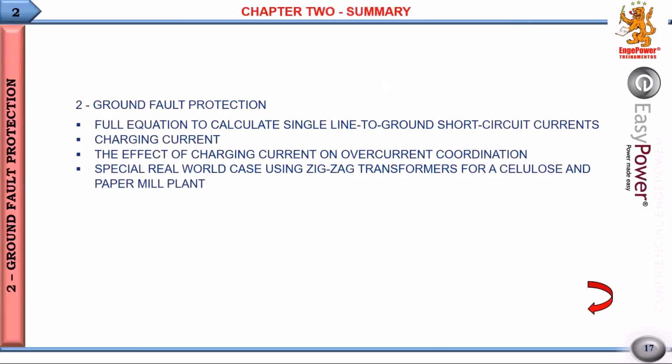Good. About negative sequence, there's something very important to note that I didn't tell you. For negative sequence, just like the fifth order harmonic, we said that there is a restraining torque that provides more current to the motor, overheating the motor.